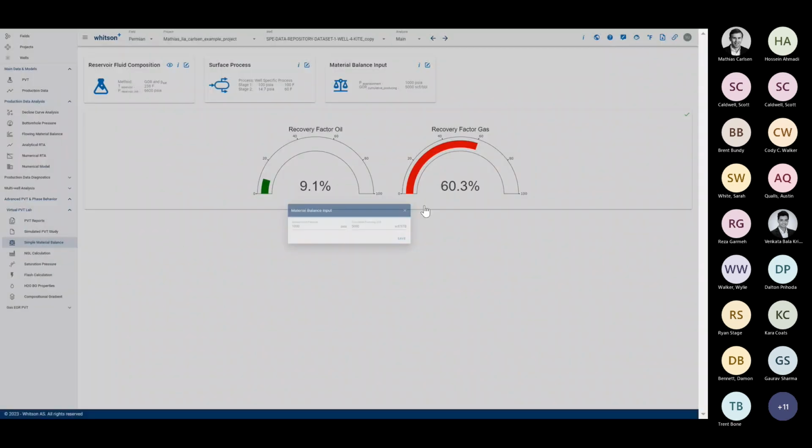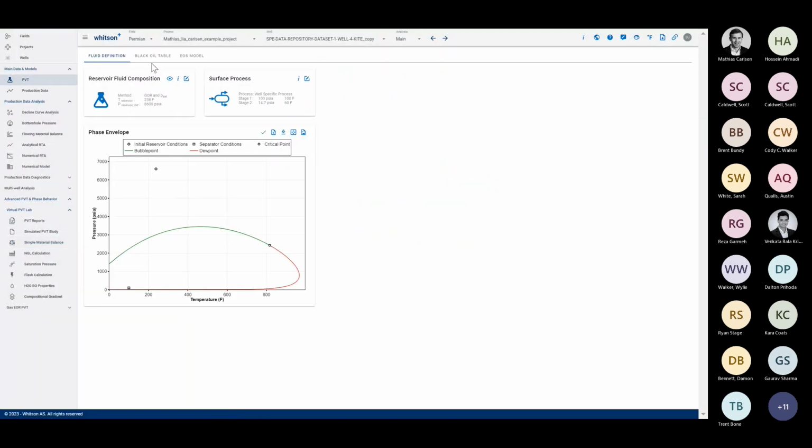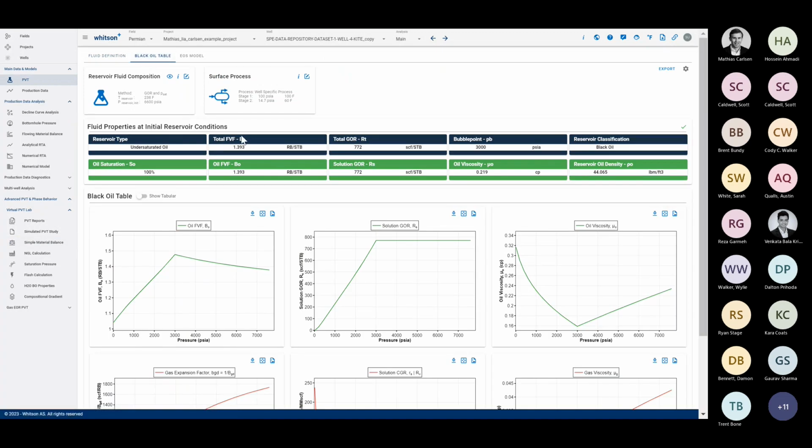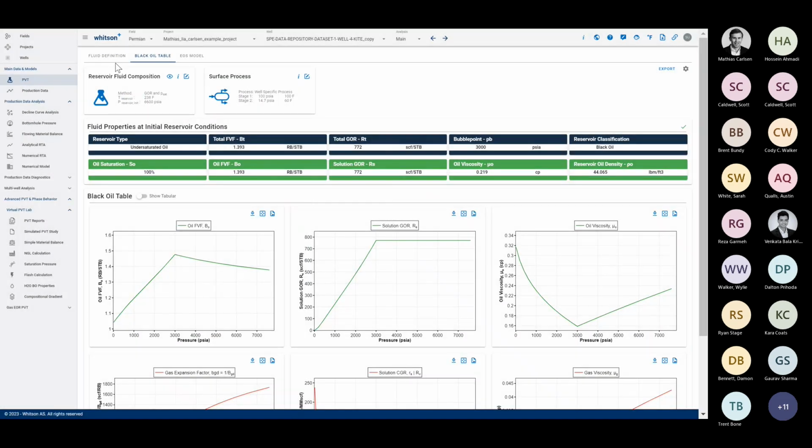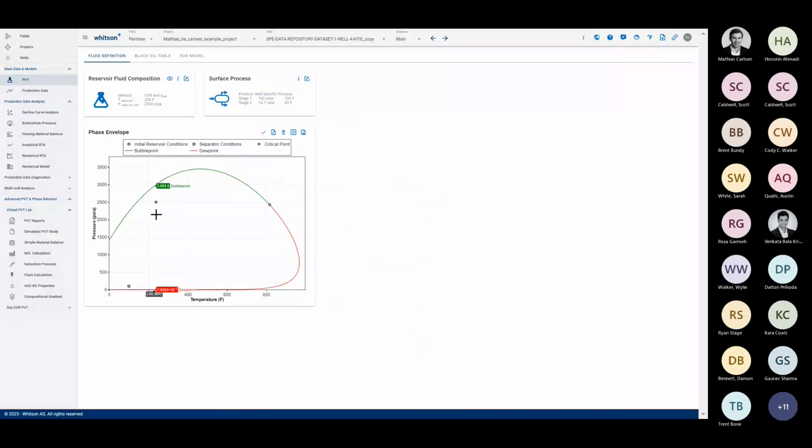What I wanted to show here is, I'm stressing this thing about these formation volume factors, these BTs and RTs, that they are really helpful. For oils, they're the same as BO. That's fine. But what if I change my pressure now to go down below the saturation pressure? Let's say I make my reservoir pressure 2,500. What actually happens then is that now I'm already inside of the two-phase region.